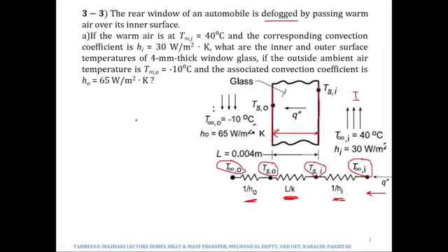So we have to find out the temperatures at two surfaces, Tsi and Ts0. Now in order to find out Tsi and Ts0, how can you find them? First of all, you can apply the convection expression between this surface Tsi and T infinity I. Q is equal to Ha delta T, so Q is equal to Hi multiplied by A multiplied by Tsi minus T infinity I. So we do not know Q and we do not know Tsi, and we do not know area as well.